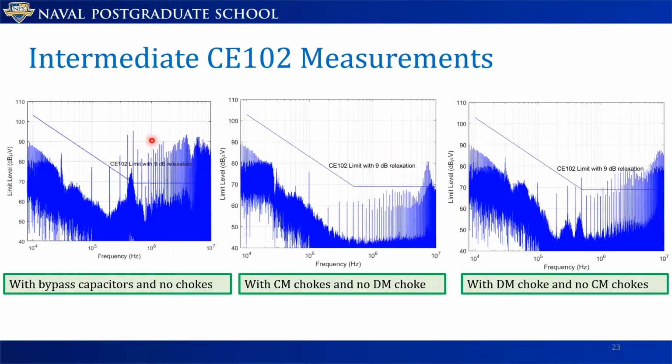If you don't put those clip-on chokes, we exceed the limits. But see, it's not at the lower frequency, only the very high frequency. And this is due, of course, to the layout of the circuit. We didn't try to minimize this. This was not really within the scope of our project. But then we tried to apply common mode chokes, and this is the result.